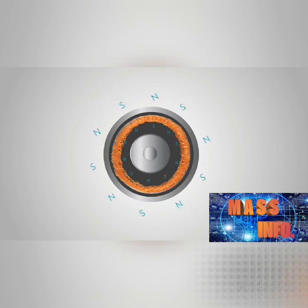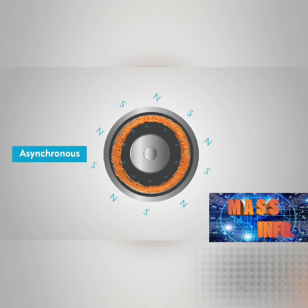Now, the induced current in the rotor will also produce an alternating flux field around itself. This rotor flux lags behind the stator flux. The rotor velocity is related to the rotating stator flux field, and the rotor rotates in the same direction as that of the stator flux. The rotor does not succeed in catching up to the stator flux speed, or is not synchronized, hence where the type asynchronous is derived.